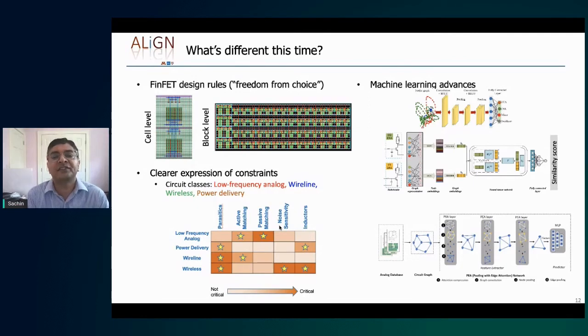Not because this is the analog designer's desire. An analog designer would prefer to work in an older node, which has lower variation and so on. But because chips have to be integrated with both digital and analog parts together, it's inherently required that the analog part must be close to the digital part, and that pulls it down to lower technology nodes.